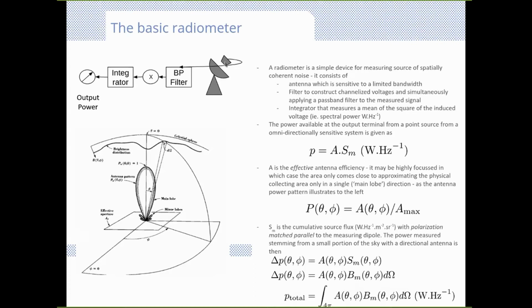It's also important to note here that the measuring device itself essentially acts, to some extent, as a bandpass filter in itself, just because of its physical properties. Now, the engineers out there may be familiar with this already, but I'm going to remind you of the basic transmission line theory, which is that you'll have a standing wave on a closed transmission line. If you open that transmission line, then you have essentially a dipole that is either vertically or horizontally aligned.